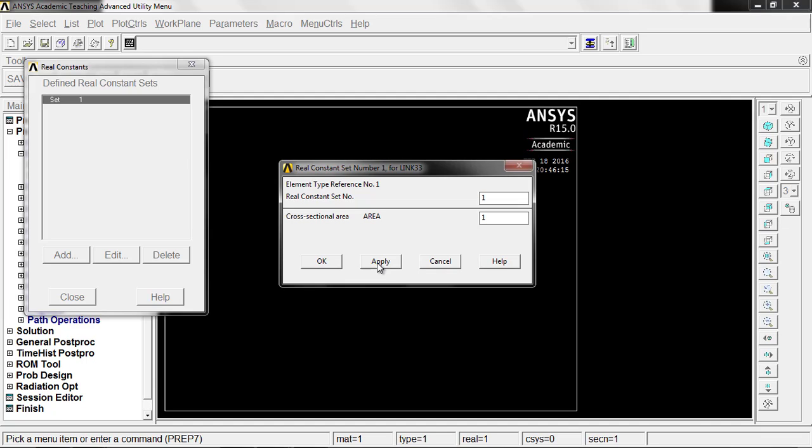But what we found in the past is that it needs each different. If you're going to have different conduction coefficients, you should have a different real constant for each conduction coefficient. So we're going to create 4 total real constants, and then 3 different conduction coefficients and 1 material for convection. So we'll see that here, but again, we should do 4 of these.